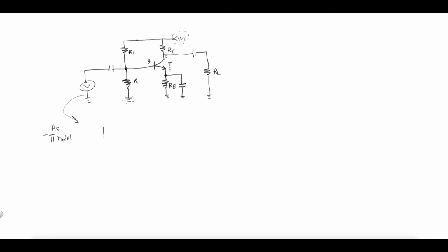So let's start with our source to ground. And let's look at this point here, from here to here. Well, what is that? That's a short. So a coupling capacitor will be shorted at certain frequencies. Assuming we are at the operating frequency, any voltage drop here in AC will be minimal, which means the impedance at that level is minimal. From this point to ground, we have R2.